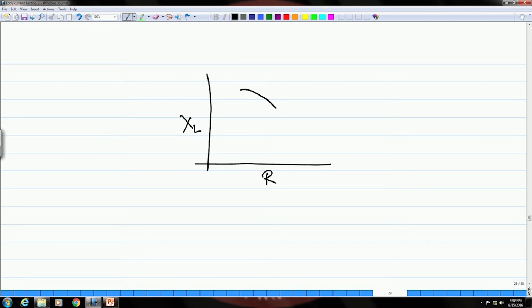So, let us say you start increasing the thickness in this manner by adding, let us say this is the first sheet, and then you are adding the second sheet, third sheet, and so on. As you keep on adding the sheets of brass, the thickness will increase, and this is how the thickness curve will be with respect to the eddy current.